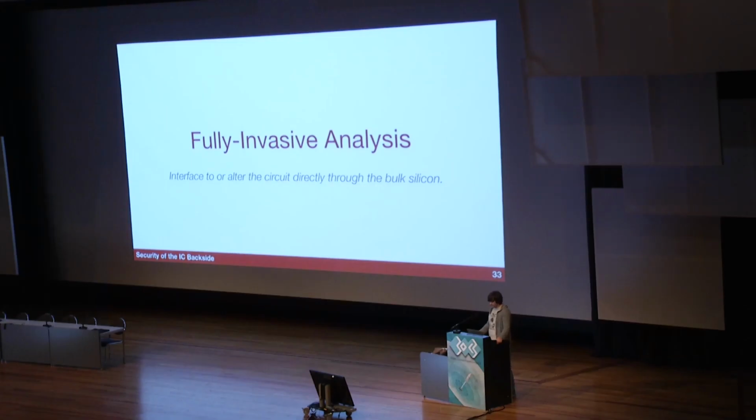It won't be random. It'll have data which differs from every other chip, but it'll be the same every time you power down this device and power it back up. So it's like a unique fingerprint. And so you can see that it's really stupid to use SRAM here as well, because this is a really effective technique for reading it out. But anyway, then we got into the fully invasive stuff that we did.